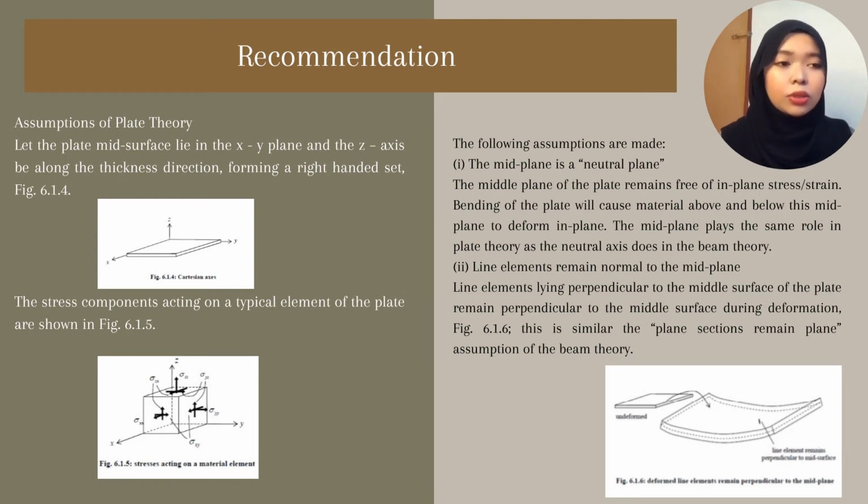Second, line elements remain normal to the mid-plane. Line elements lying perpendicular to the middle surface of the plate remain perpendicular to the middle surface during deformation. Okay, figure 6.1.6, this is similar to the plane sections remain plane assumption of the beam theory.